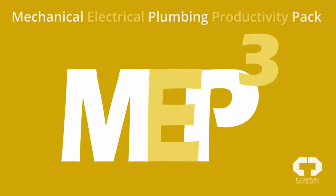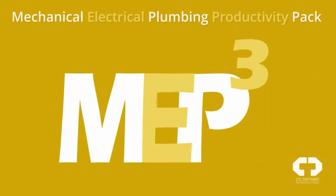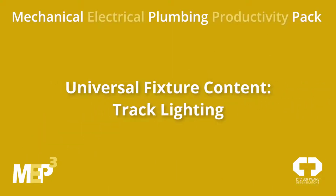Welcome to this tutorial on CTC's MEP Productivity Pack for Revit. In this video, we will review the Universal Fixture Contents Track Lighting. The Electrical Productivity Pack features a workflow for modeling and circuiting track lighting, which calculates load based on the length of the track as required by the National Electrical Code.